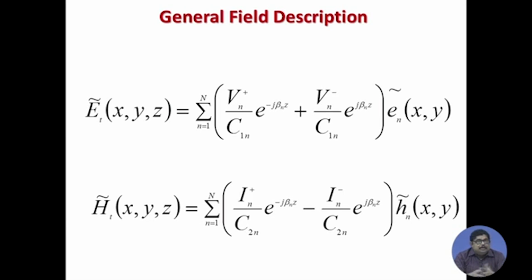So, there can be various modes possible, particularly near the discontinuity etcetera, or near the excitation, when we are very near to the source or very near to the load or very near to any discontinuity. Instead of a single mode, various higher order modes also are present. That time we can write that in the form of various modal voltage and currents. This is the description, and this completes how you can define equivalent voltage and current in microwave frequencies.